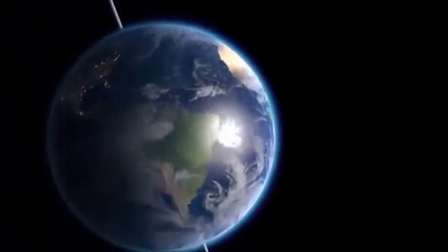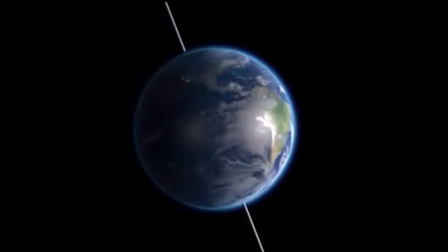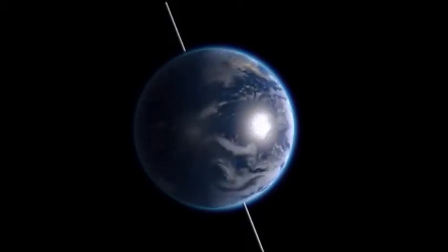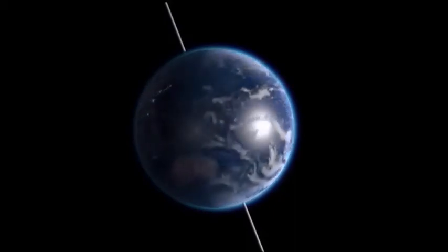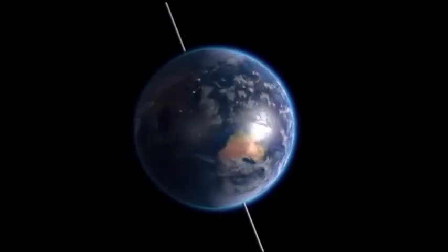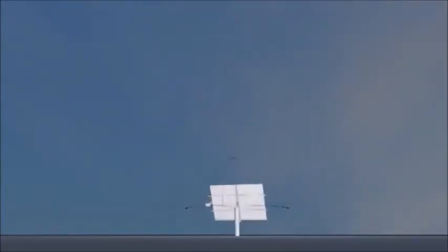Why do we need to change the orientation of the solar panels to always face the Sun? This is because of the Earth's rotation. Here you see how the Earth is rotating on its own axis, which is inclined 23.5 degrees to the perpendicular to the plane of the Earth's orbit. As the Earth rotates, different places on the surface of the Earth are illuminated differently at various points of time during the day. Thus, the need for solar panel orientation arises. In this animation, it is seen clearly how the solar panel is changing its orientation during the day.